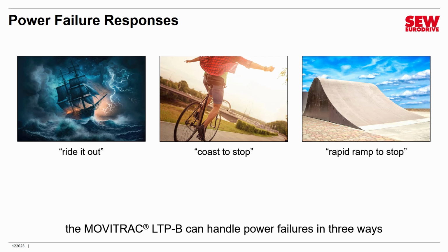The ride it out method is meant to handle very brief power interruptions where the power goes off for just a short time and then returns. In other words, kind of a power supply blip. Now, the way the system will behave if you've selected the ride it out method, it will reduce the motor speed, but it will attempt to keep running using stored energy in the VFD's filter capacitors. If the power outage is very brief, then this will work, and when the power returns, the VFD will return to normal speed. The problem with this method is that the outcome is unknown.